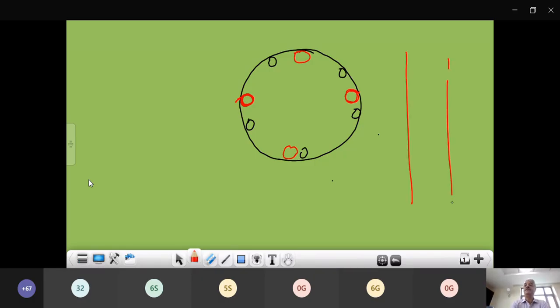Inside the pile, these tubes also get lowered with the reinforcement and they remain hollow. Concreting will not happen inside them, everywhere else concreting will be done. Now there are ultrasonic sensors which you lower in these tubes.